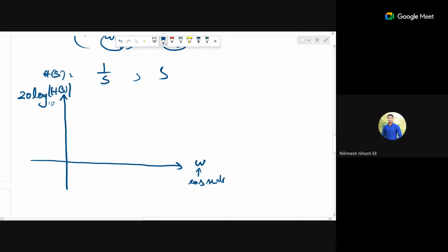First of all, you have to remember this is a non-linear scale. It is a common log, not a natural log, so that's why it's decade. You can also form 20 dB per octave. One octave is equal to 0.3 decade, so this is a general formula. Generally we consider the decade scale only, but we can also form the octave scale. In the octave scale there will be eight divisions, in the decade scale there will be 10 divisions. Simple.